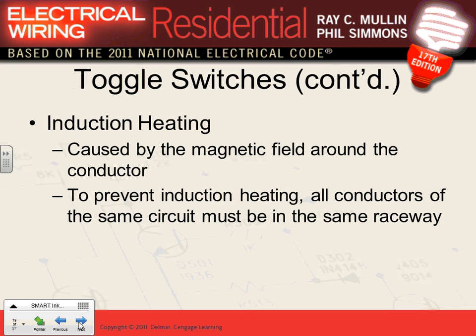How do you solve the problem? Always, if you have a three-phase system, five conductors typically, right? 3-phase, neutral, and ground, you pull them in the same cable tray, conduit, or trench. That's all, to avoid this one. Can I have thumbs up, Chad?